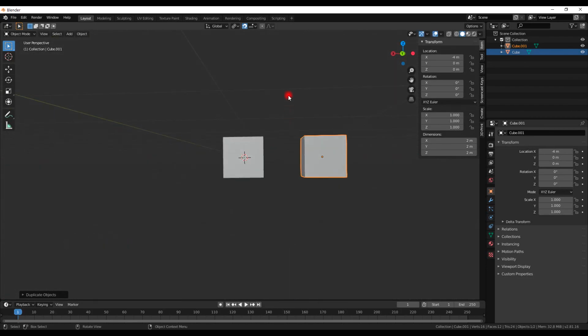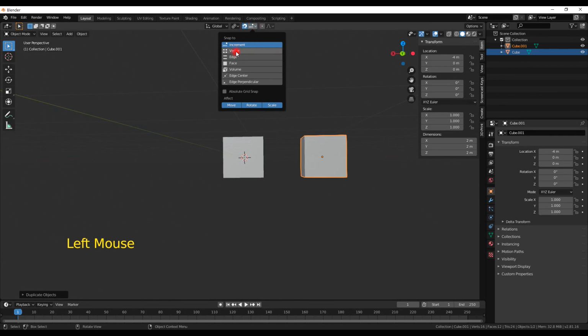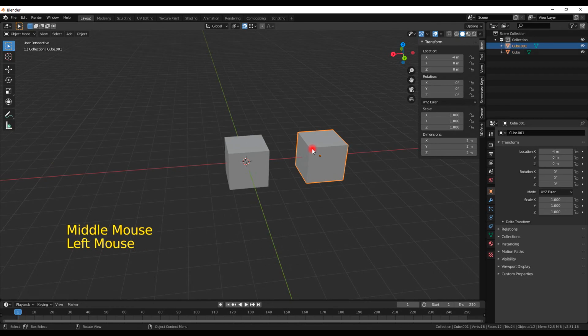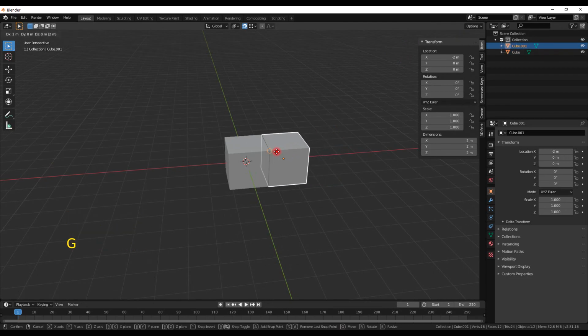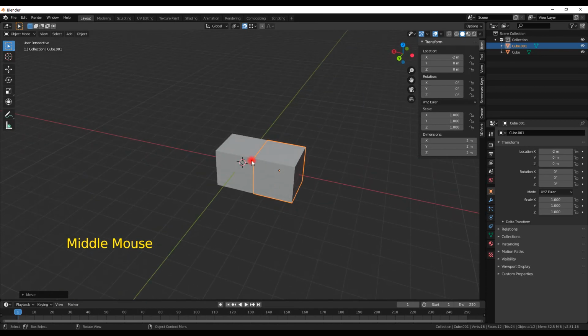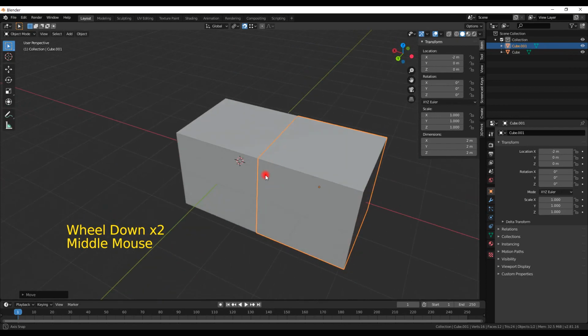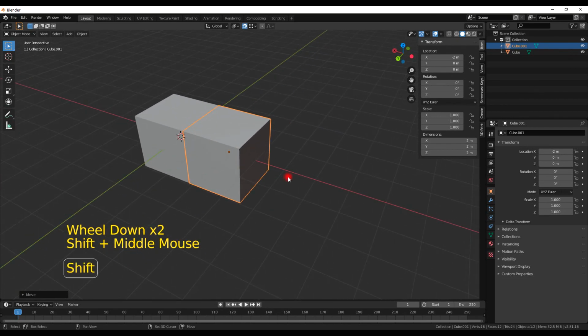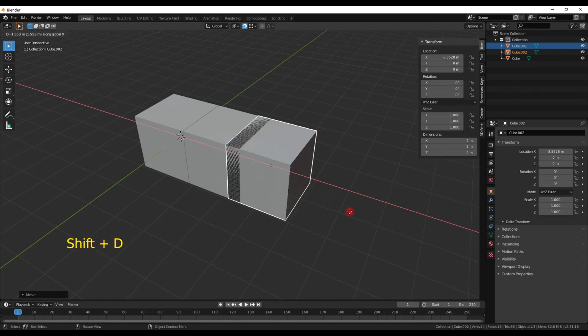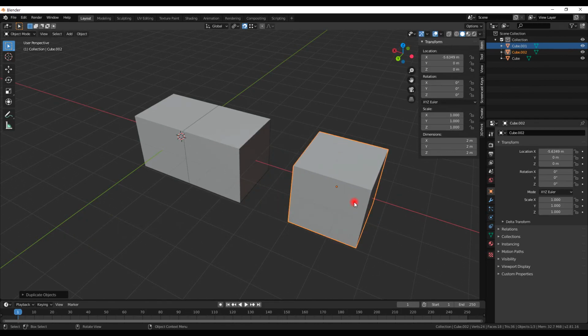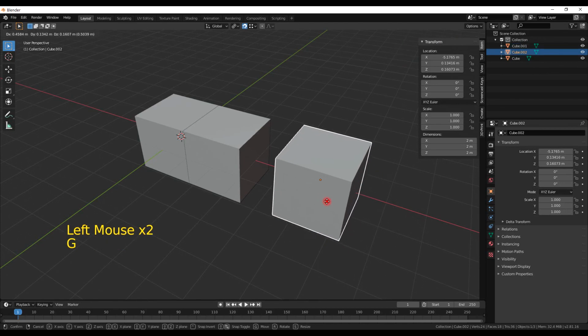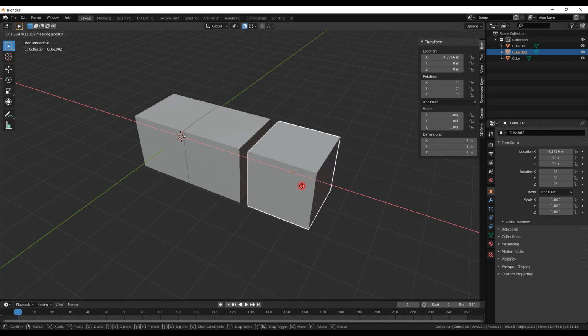Now, if I have turned on Vertex, and I will then move this cube close to the other one. When I go all the way close to it, it will snap so that the vertices are now joined. This is an exact match. If I do the same thing here again, I will make a copy of this on the x-axis and then move this with the snap on closer to the other box. It will snap when it goes close enough.